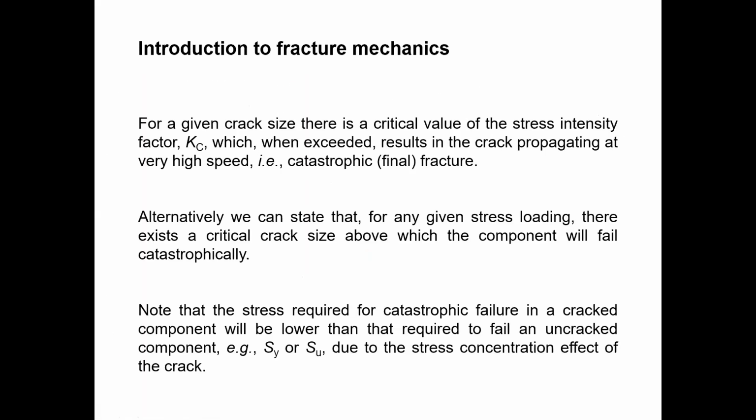Note that the stress required for catastrophic failure of a cracked component will be lower than that required to fail an uncracked component. For example, yield stress, yield strength and ultimate tensile strength. This is considered the effect of the crack.